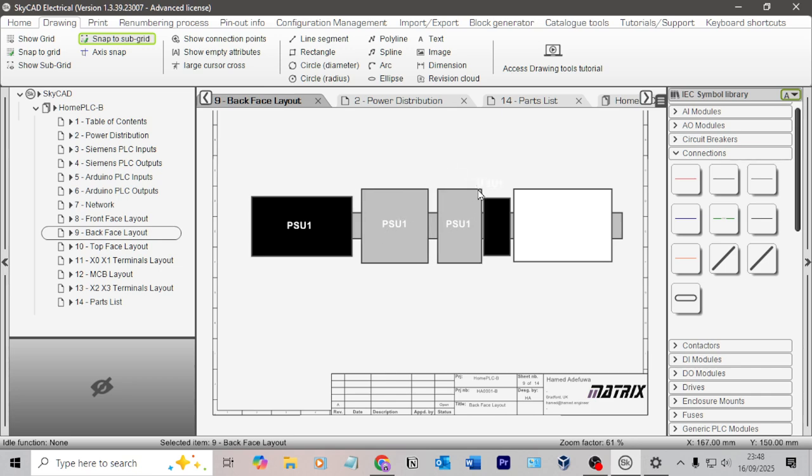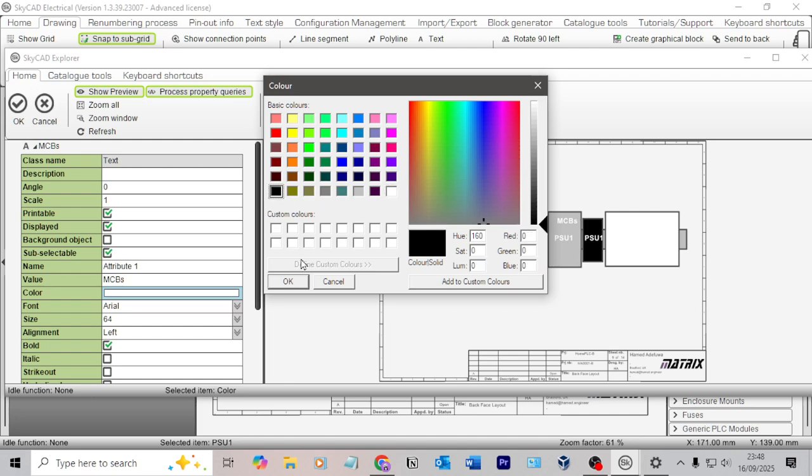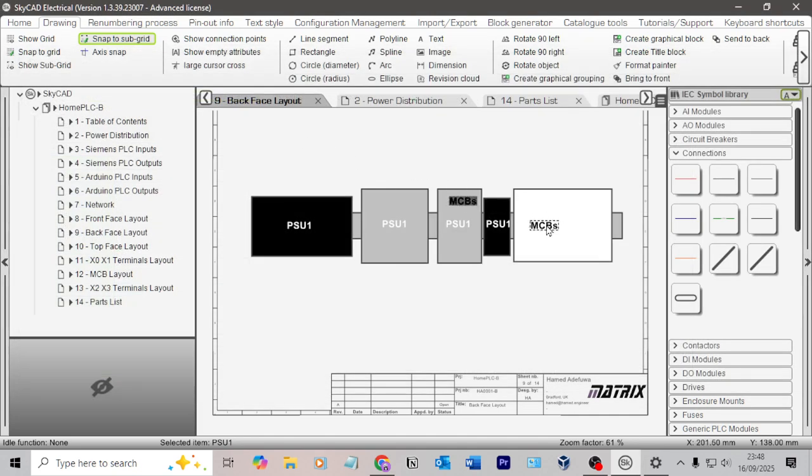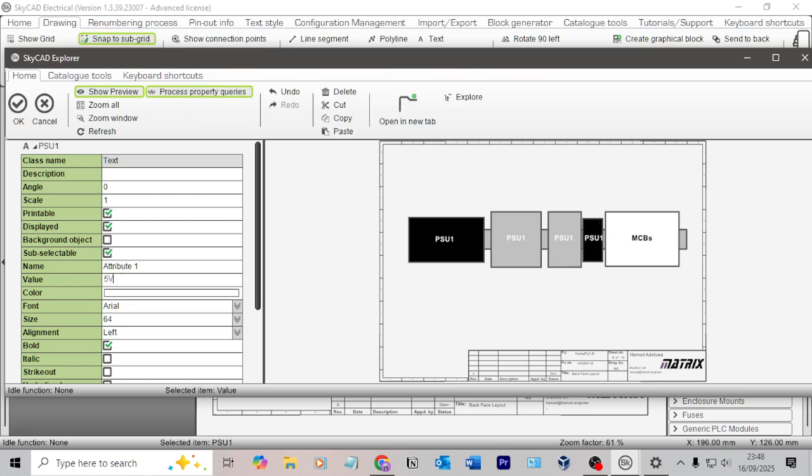I think ultimately you're just doing it because you want the panel builder or your production team or whoever's building the thing to have an idea of what they're doing, basically, right? So it's just like a visual aid. Ultimately what matters is the schematic, and that the schematic's correct. Some people with their layouts do a whole bunch of dimensions and stuff, so you can make sure they put it bang on precisely where you said. So again, you can do that. It's up to you. So let's just put 5-volt reg.